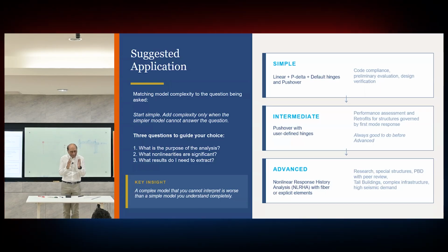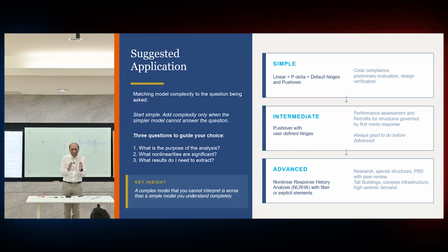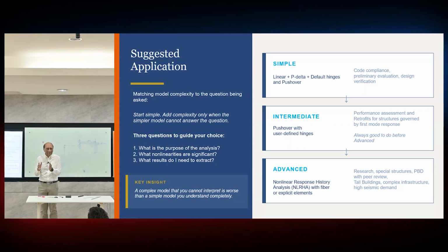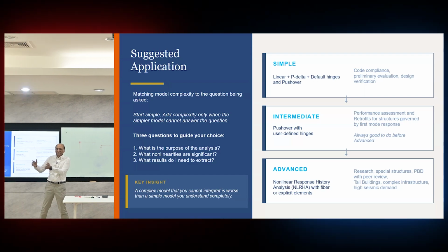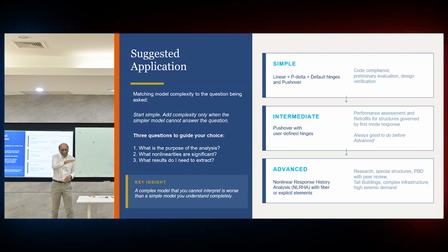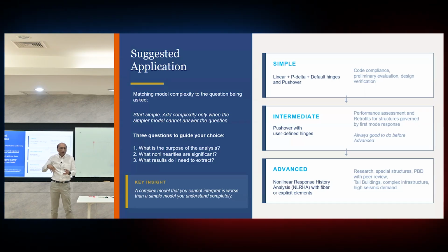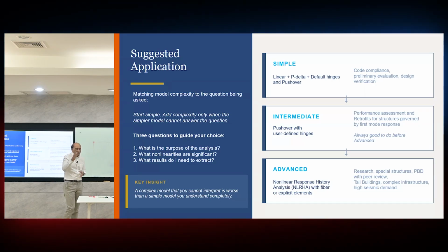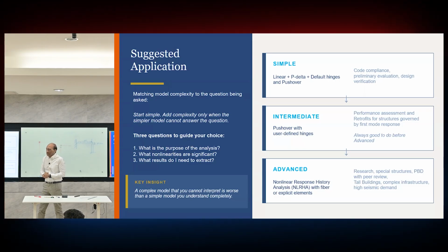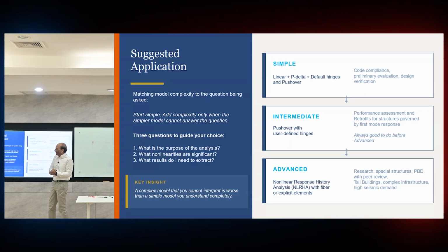Next one is a little bit of nonlinearity, P delta. Then you see what is the effect of the P delta. Then you go, okay, pushover plus P delta. Then this one, then this one, then this one. Then you have all the results to compare. So you know that nothing will go completely out of hand. So you can then trust them one by comparison with other methods. That's the way that you keep a control on the final output.